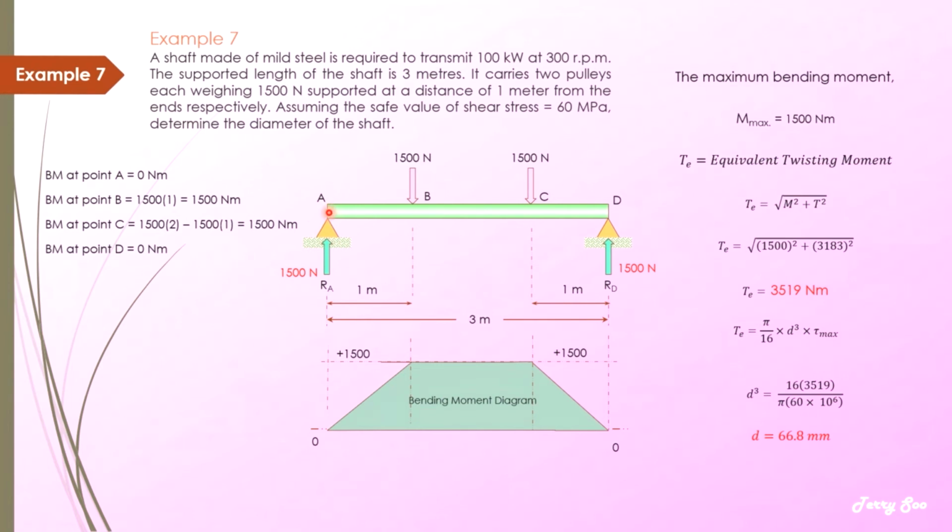So you have the force 1500 multiplied by the distance. The distance from this point to the force is 0. So you have 1500 multiplied by 0, which is why it's 0. Then you move the reference to point B. Then you have 1500 times 1 meter to the point I place here, causing bending upwards. So you have 1500 times 1, which is positive.